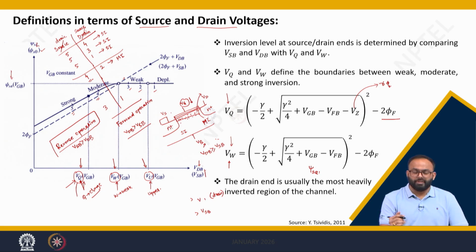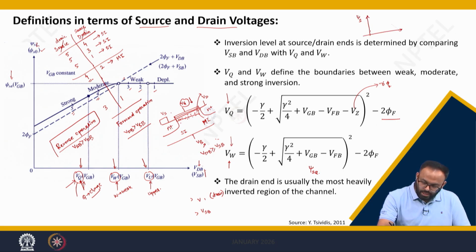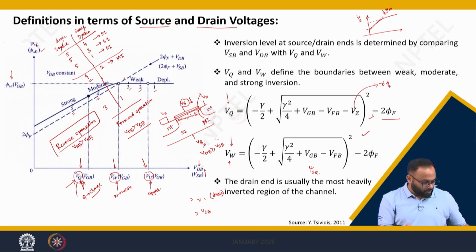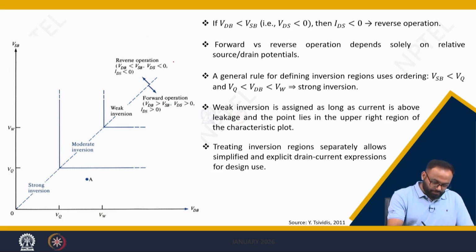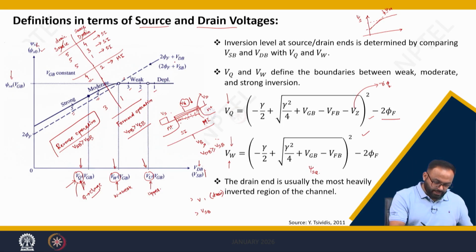the surface potential which is fixed at depletion and weak inversion and given by a straight line. If you remember that graph, this is the surface potential and it will be given like this. So this line was psi SA. Beyond the onset of weak inversion, when you entered strong inversion, the surface potential gets pinned to the 2 phi f value, correct. So that's what we have already discussed and derived these formulas. We are going to use this formula to define our region of operation, as I already explained in terms of this graph, mentioning a few points in our graph, that's 1, 2, 3.